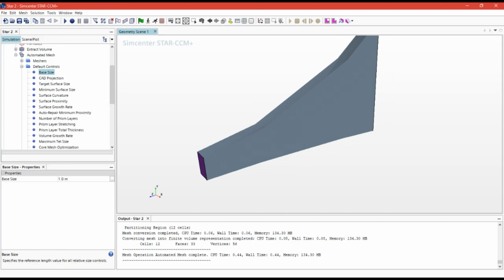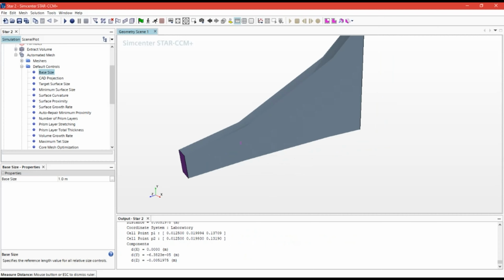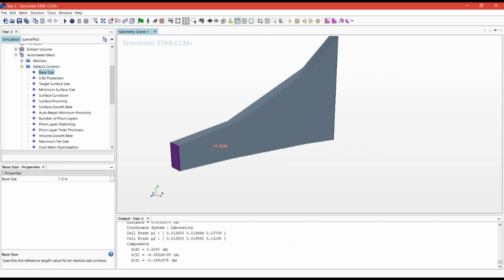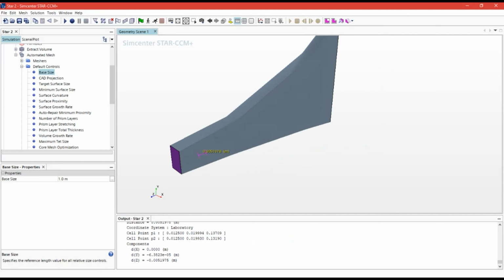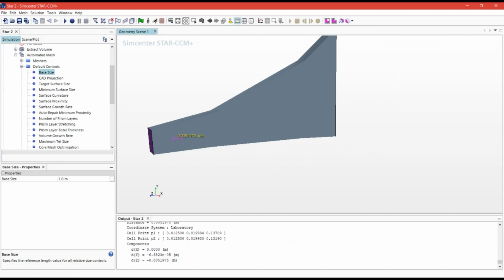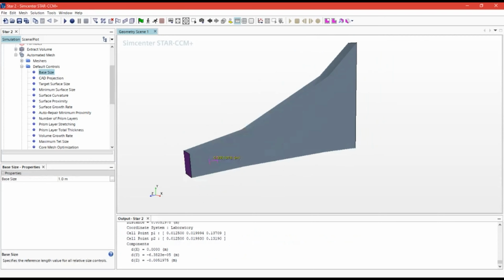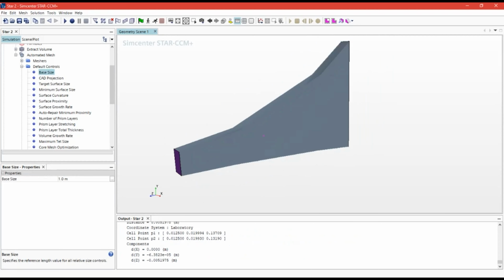The way to do that is to click on this ruler icon and think, yeah, that's probably a good cell size to use. They'll probably model our conditions as we wanted them to be. If our result isn't converging, if we're not getting the proper result that we're expecting, maybe we need to use a finer mesh. But I think this is probably a good starting point.